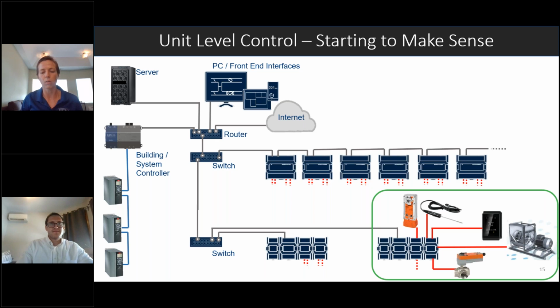So in your typical or older generation of controllers where they're leveraging that BACnet MSTP, LonWorks, or proprietary communication, you typically had your unit controllers, also known as your field controllers. And then you typically have those wired up to a building controller or a JACE, a more powerful controller that does more higher level functions, typically has more horsepower, things like that.